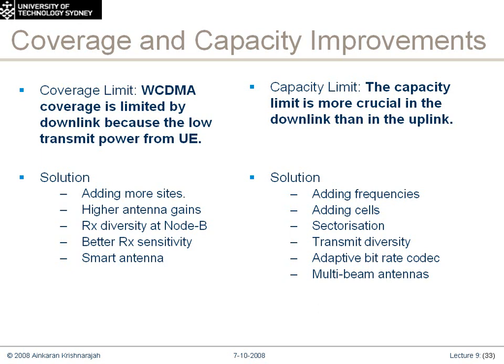Another one that's probably more current is MIMO, multiple input, multiple output, which is something you might be familiar with from wireless LAN and WiMAX and LTE. They all use MIMO or will be using MIMO. The complication with MIMO, though, is that you have to upgrade all of your base stations to have 2 antennas. So you can imagine the complexity to go to every single base station and make that happen. And secondly, the terminal needs to also have 2 antennas as well.